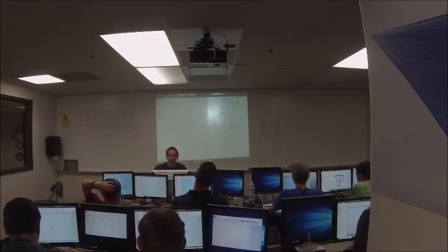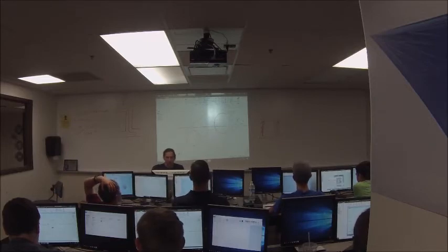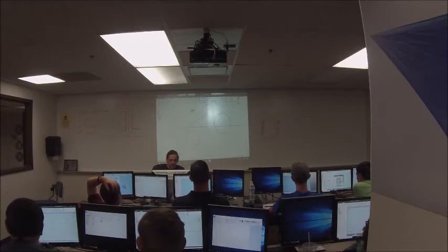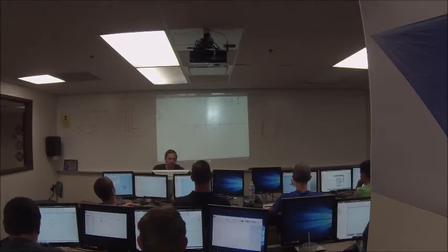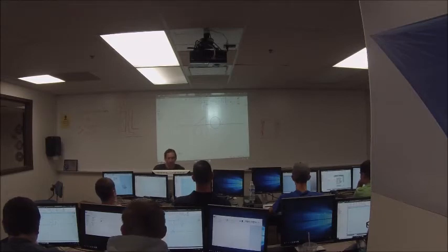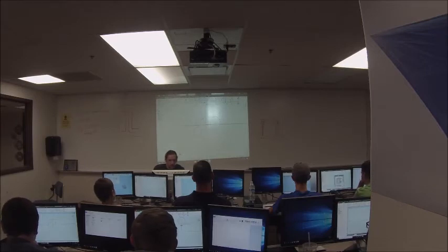This is also a very useful one, but it's kind of pretty simple. Basically, if I have two lines, there's a short line, there's a long line, and I want them to be the same length, I can click equals, click on one line, click on the other line. Now these two lines, no matter which direction they're facing, are always going to be the same length. The same thing applies to circles. If I click the equal sign, click on one circle and click on the other circle, the two circles are the same size.